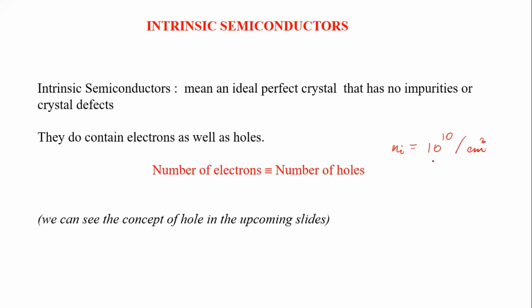Whenever a semiconductor is in its purest form and it grows, the carrier concentration ranges from 10 power 6 in compound semiconductors to 10 power 10 per centimeter cube in elemental semiconductors. Then we term them, in the practical case, as intrinsic semiconductors. Keep the word correctly: practically, we have carriers, even though they are not the ideal case, and their conductivity is low.